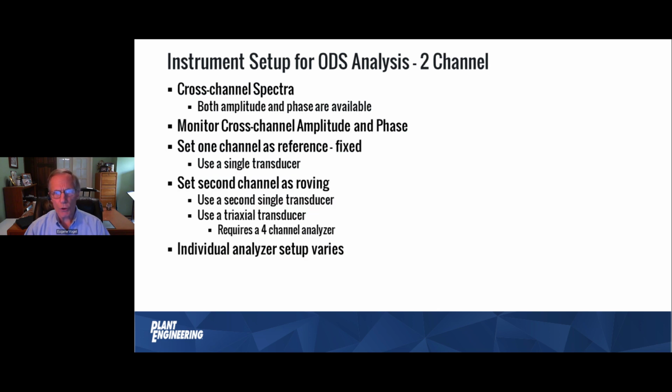You can also use two-channel analyzers, and with a two-channel analyzer, you can get this done without a reference pulse pickup. So if you walk up to this machine, you've got a severe vibration, and you want to get an operating deflection shape up, and you say, well, I need to shut it down and put a piece of reflective tape on the shaft. And the operator looks at you and says, you want to shut the machine down? If you shut that machine down, it ain't going to be back up and running again until tomorrow. It takes us that long to go through the cycle.